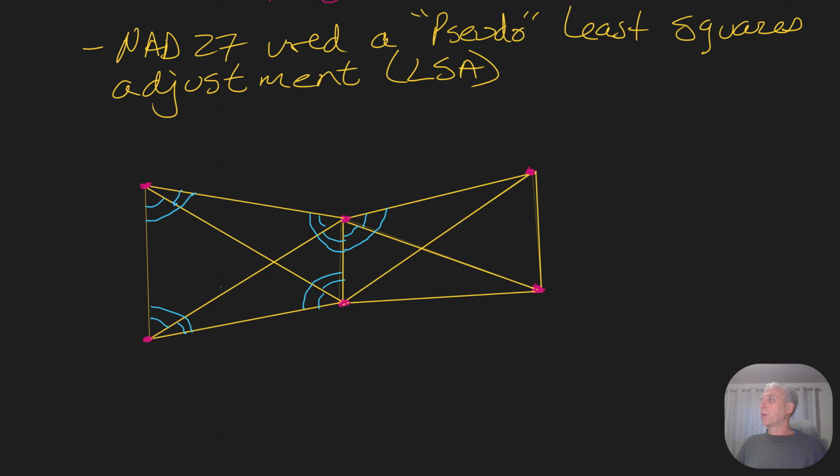And while we're here, we would get those interior angles. We might also get the entire angle, right? And we just keep going. And by the time we're done, we have all of these sets of measurements and these angles. And we would use the data we collected to perform a least squares adjustment. So we'd have a least squares adjustment, which would result in residuals.